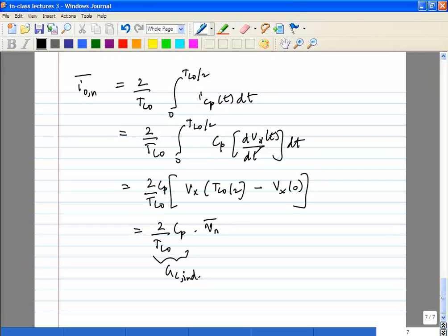So this is the conversion gain for the noise for the indirect path. What do we see? Of course, the conversion gain increases with the frequency. So definitely, if you have a higher frequency LO, the noise through the indirect path will tend to be higher. Usually it will be much lower than the other noise, but it's something to keep in mind, because it depends on the parasitic capacitance as well as your FLO.